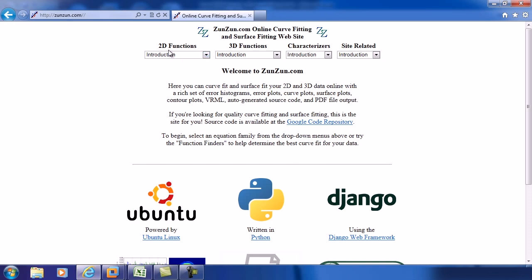The two types of functions that we're going to be interested in are 2D functions. You could think of this as a table with two variables, where you're going to have your input variable and your output variable. For example, the input variable for one of our examples is going to be the percent methane from the sensor, and the output variable is going to be the correction factor. For the solar tracker, our input variable is going to be the angle from the sensor or inclinometer encoder, and the output is going to be the correct angle for the actual heat transfer fluid pipe, the receiver. So that's a standard f of x, where x is your input value and y is your output value. F of x equals y.